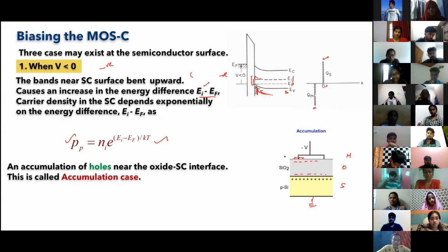When you put negative charges, you have positive charges developed. You put positive here, then naturally it will be negative on the other side. It's a kind of polarization. To compensate this, you have negative charges accumulated here. So what you do, you are applying a negative voltage to the gate. You accumulate charges in the interface of the semiconductor side. It is the oxide semiconductor interface.